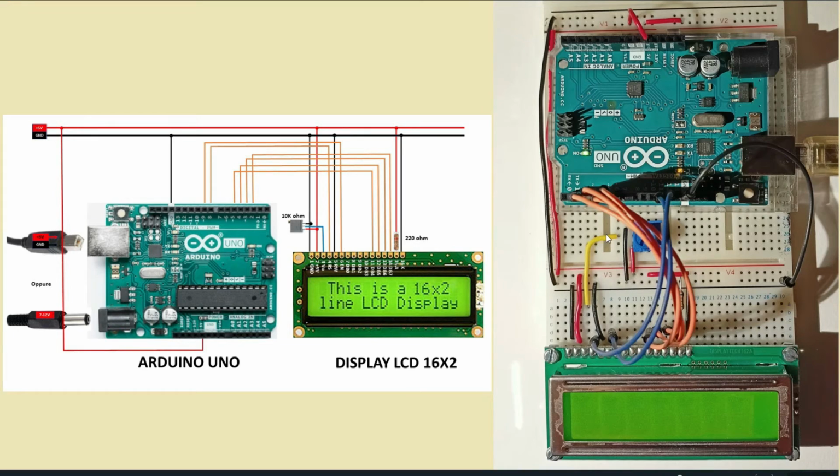Then I connected the 2 ends of the 10K trimmer, which we have here, this trimmer. I connected them through this jumper and this one to 5V and to GND, and with the yellow cable I brought the cursor to pin 3. Here it is yellow, while on the connection diagram it was a blue cable.